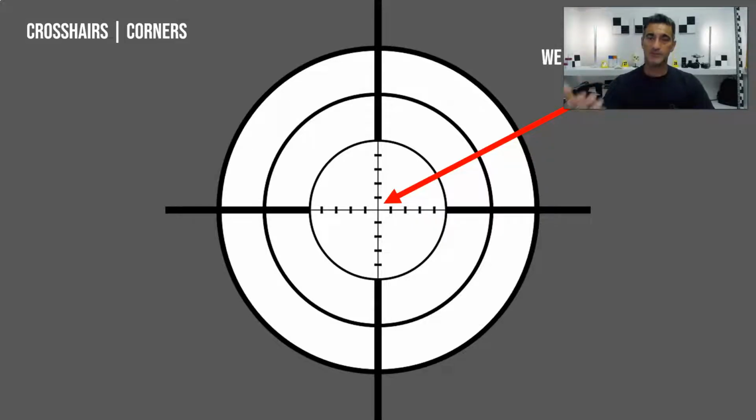And the problem is, let me give you a very simple example of way back when people were doing things like total station surveys. You'd say, I want to know the distance between one pole on one side of a road and maybe another pole. And it's like, okay, no problem. So somebody goes and measures it, and they've got 2 points. But the problem is, you don't know where they took the measurements from. Was it the inside of the pole? Was it kind of on the side? Did they measure the diameter and then choose the center? So